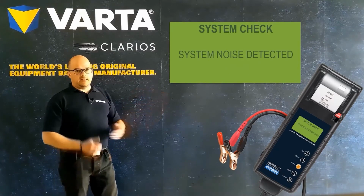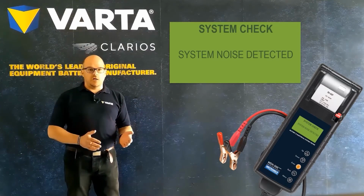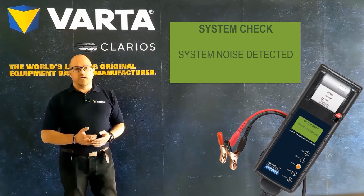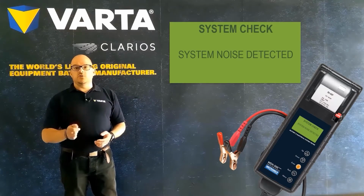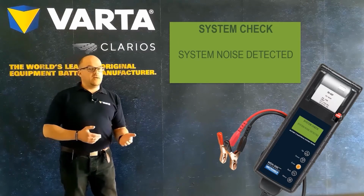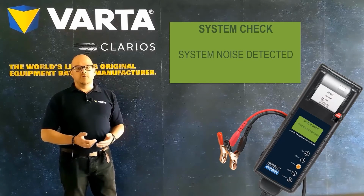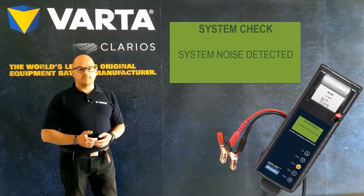System noise detected. This is due to any electrical component using charge while the battery test is underway. But this is usually seen if there's a larger than normal consumption, such as a fuel lift pump or an injection solenoid, or it can be a faulty component such as a bonnet pin switch.